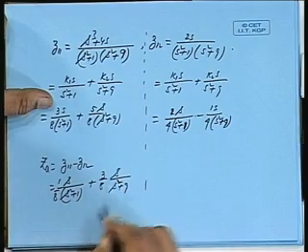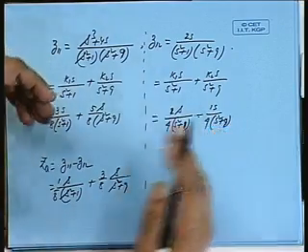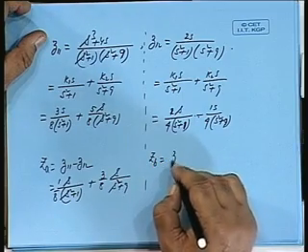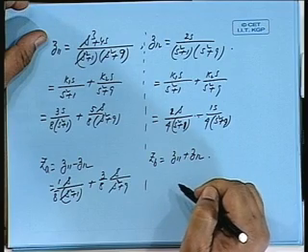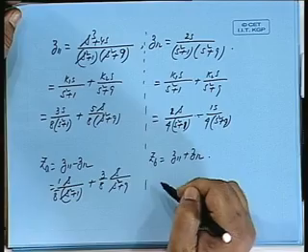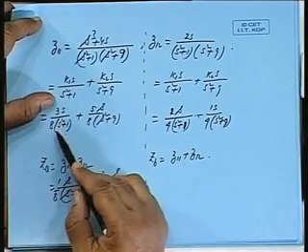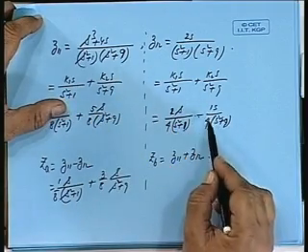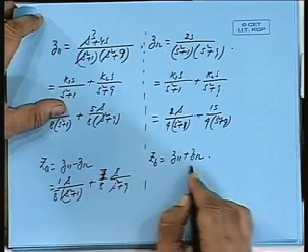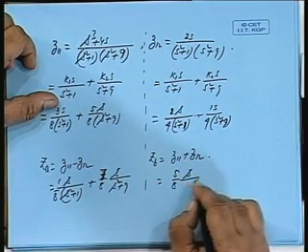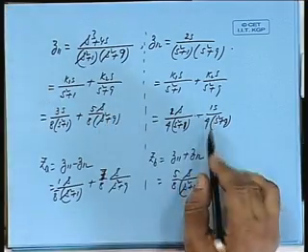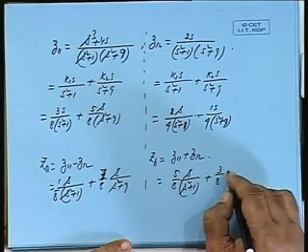So, both are positive real, whereas Z12 may have a negative sign, but you have to see whether after combining everything it remains positive or not. ZB, similarly ZB was Z11 plus Z12. 5 by 8 minus of ZA. ZA is Z11 minus Z12. So, 3 by 8 minus 1 by 4, 5 by 8 plus 1 by 4. So, 2 by 8, 7 by 8. Similarly, ZB will be Z11 plus Z12. So, 3 by 8 plus 2 by 8, 5 by 8 s by s square plus 1, and if I add this with this, this will become 3 by 8, s by s square plus 9.